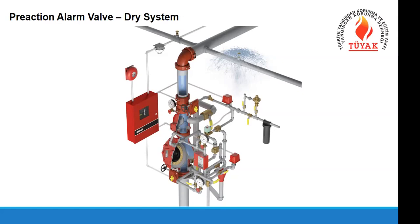Here we see a double interlock pre-action system, and with this kind of system, the only way you will see water coming from the sprinklers is activation of the sprinkler and the detection both activated at the same time. So for example, somebody hit the sprinkler by accident and it's open, and we don't have any fire in the room.